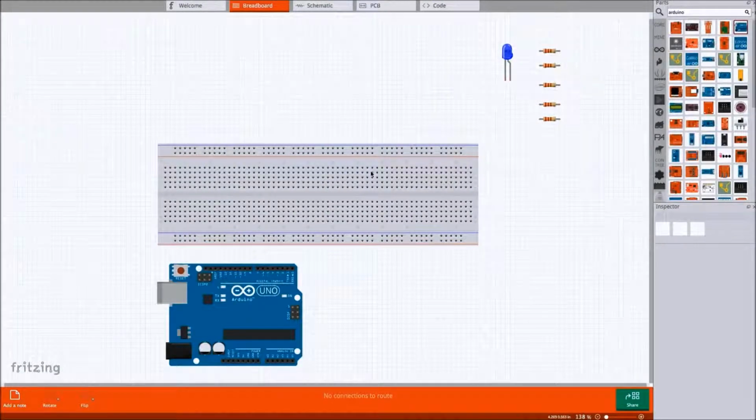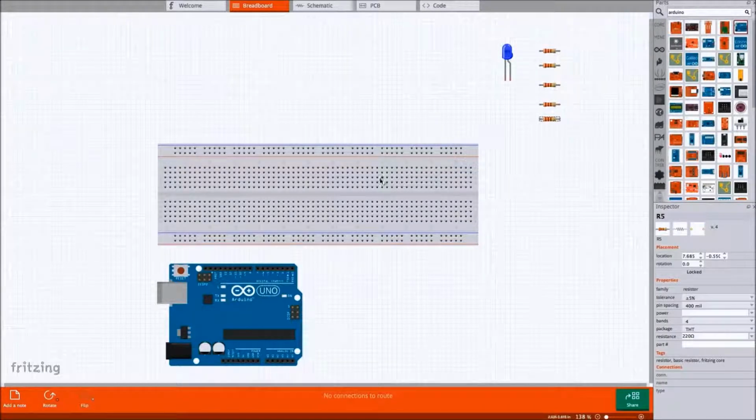In order to make a pulse wave circuit, you have to follow the code by using the right pin numbers, and you also have to wire everything in parallel. Now, you're going to need a breadboard, an Arduino Uno, 5 LEDs, and 5 resistors. You also need 6 wires in all, 5 being red preferably, and 1 blue. The blue wire represents your grounding wire, the red wires represent your positive wires where the electricity is going to initially flow from. So, we are using pins 3, 5, 6, 9, and 10.